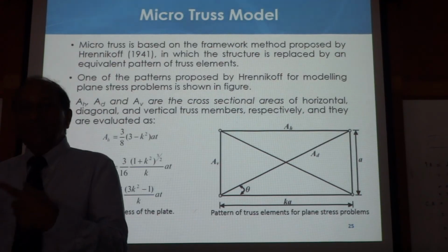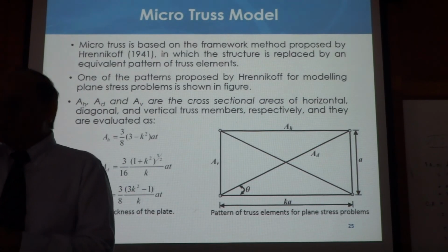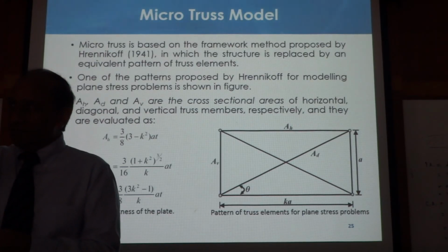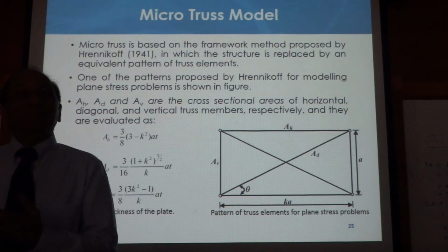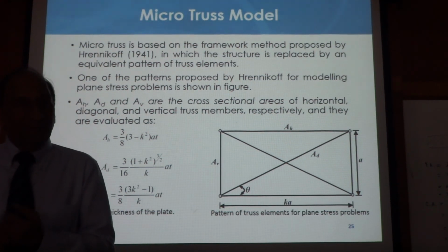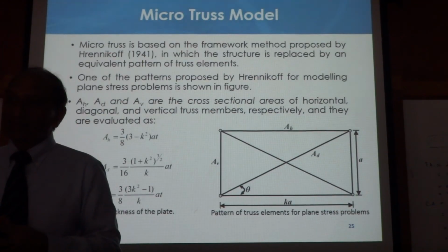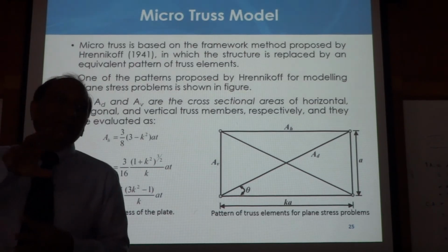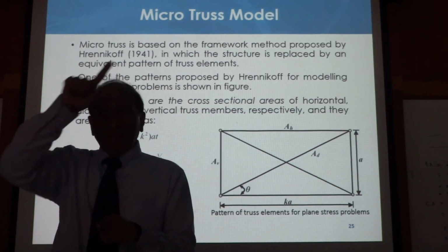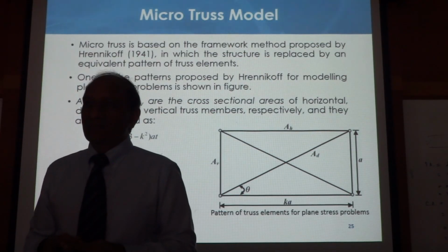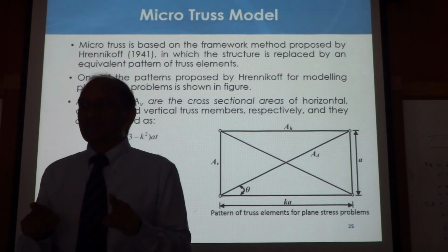So we still use this idea in modeling of the masonry walls. If you have a wall inside a building, right? How do you model a wall? It's too complicated, using many types of elements. It's too complicated behavior. There are many bricks there, there is mortar there, so many things, you can't model it, right? So normally, the codes and these methods, we say, okay, you can replace a wall by an equivalent diagonal. That means the entire wall is replaced by an equivalent truss element, right?